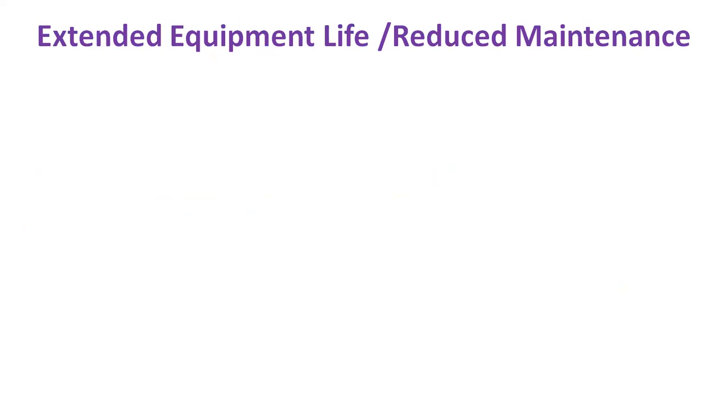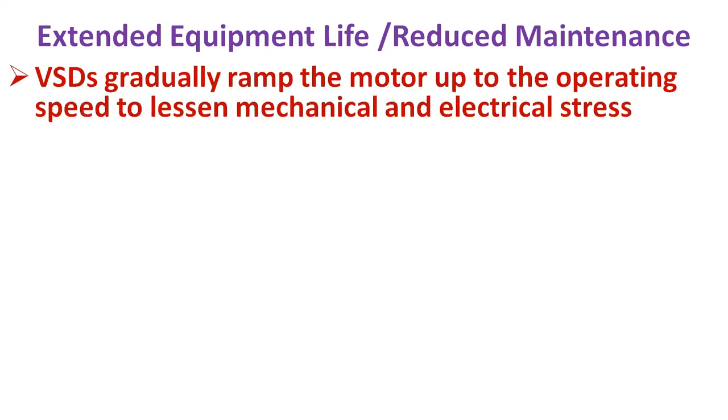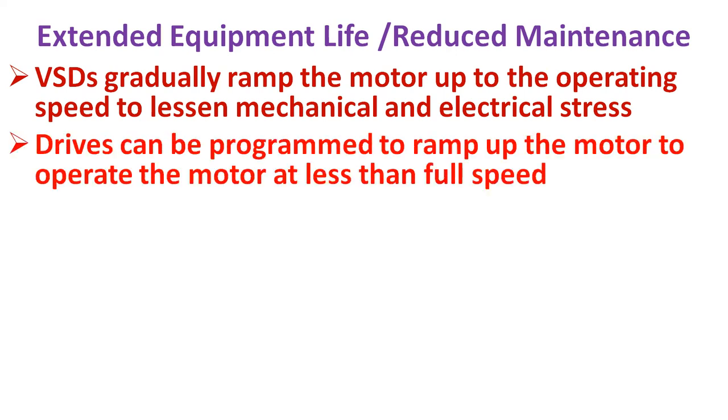Many open loop variable speed drives do offer slip compensation, which enables the drive to measure its output current and estimate the difference between actual speed and set point. Then we have extended equipment life and reduced maintenance.